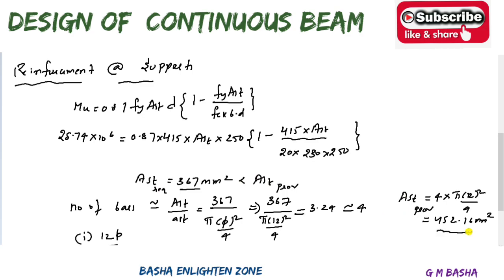And one more thing I am telling: at the support there will be one more moment, which is Mu equal to 25.7 kilonewton meter. If I check with this condition, what happens? Your area of the steel will be lesser, which is lesser than 367 mm square. And if you confirm with the area of the bars, maybe you will get 12 dia bars only, but it is not that much lesser, it is very near. Maybe you will get 12 dia bars, maybe 3 in number.